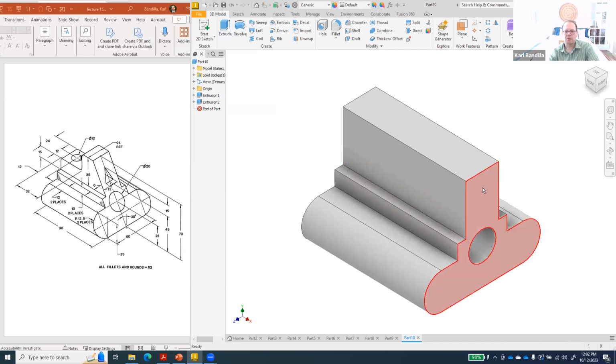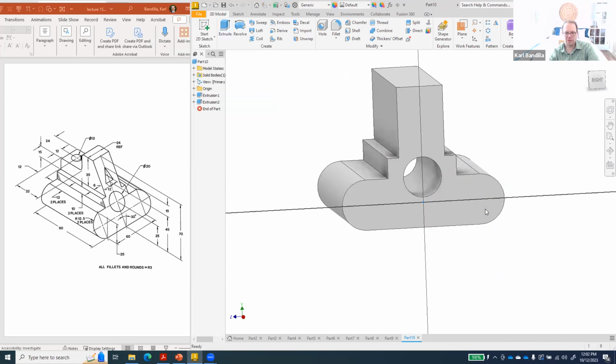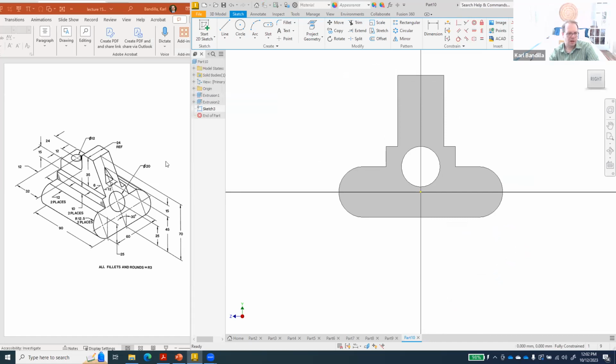Got our main hole, and then our little triangular shaped hole. Now that line, the bottom, is supposed to be 12 side to side. So what I suggest we do, we draw ourselves a line that is halfway, so 6. And then we draw a line, we don't know how long this is, but we know it has to go up there. And then we dimension stuff to make sure it's the right size, and then we'll finish that triangle.